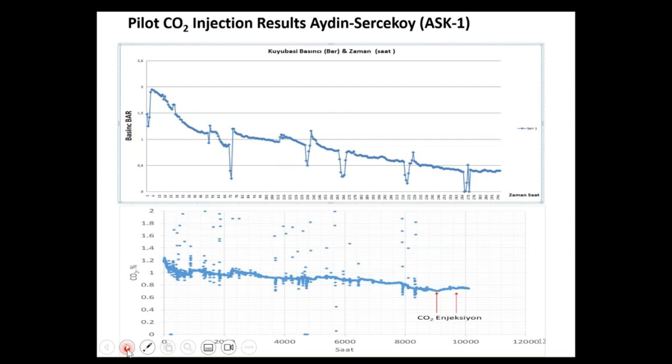And I want to show something. This is usually, as I said at the beginning, the biggest scare. I know some other companies in Turkey were trying to directly inject CO2 into the brine with a compressor to the line without any secondary string, and immediately wellhead pressure increases after a certain point. It is called bubbling at the wellhead. They will not be able to inject CO2,